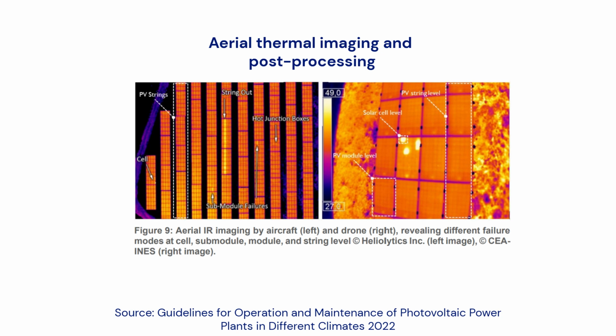This failure data, which appears as distinct thermal patterns, typically has very high spatial resolution, ranging from system level down to individual cell level details. Once properly labeled, this information enables maintenance engineers and field technicians to quickly diagnose, classify, and address PV faults, as well as identify their root causes. When applied correctly, aerial infrared and visual imaging is therefore a very powerful diagnostic tool.